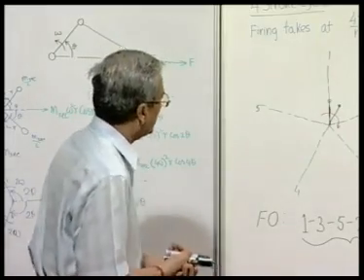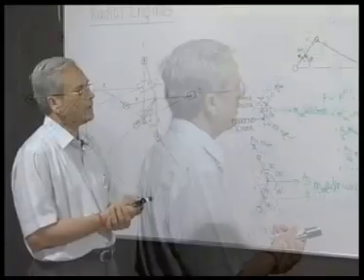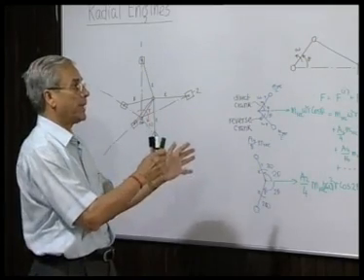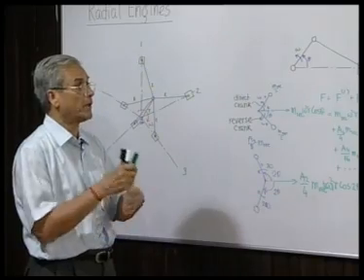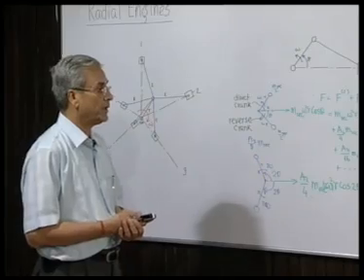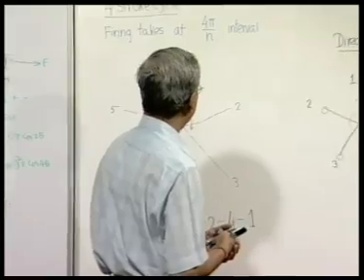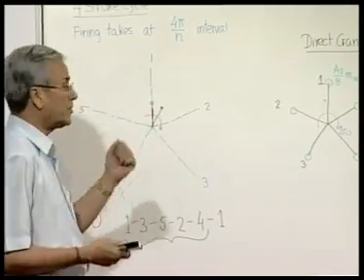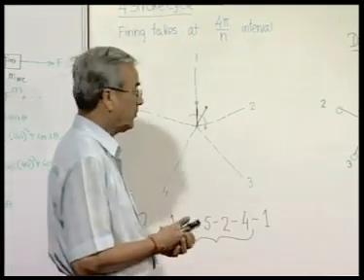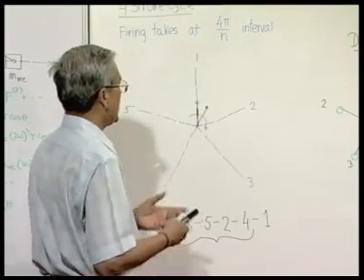And radial engines, IC engines, these we have seen what the situation is. We have also seen how we can actively attach some mechanism to an engine to produce unbalanced forces, which can balance or neutralize the unbalanced forces of the original engine. We have also seen the importance of firing order, and lastly, in the case of radial engines with 4-stroke cycle operation, we must always have an odd number of cylinders if we want the firing to be uniformly placed and all the cylinders to be fired.